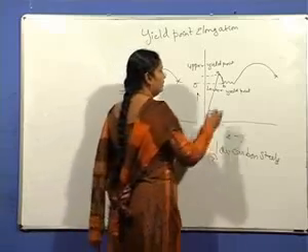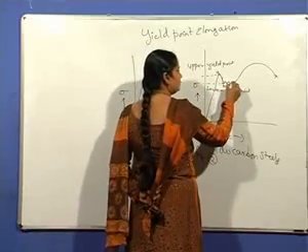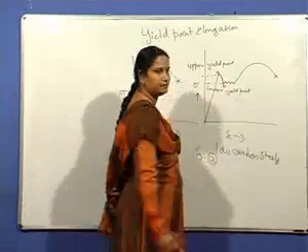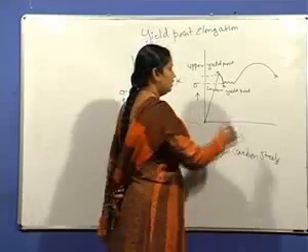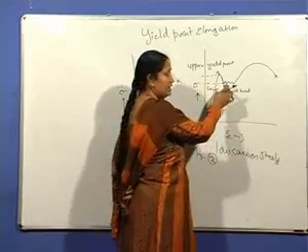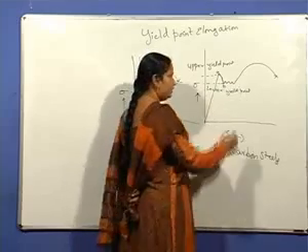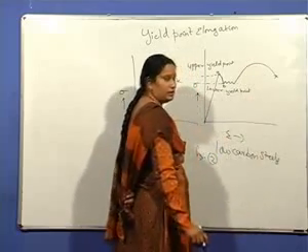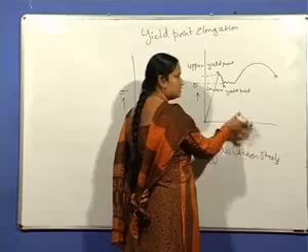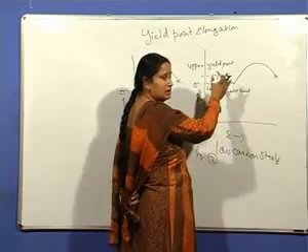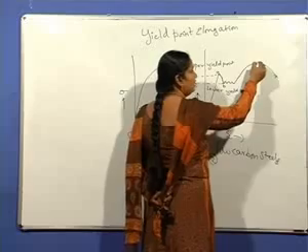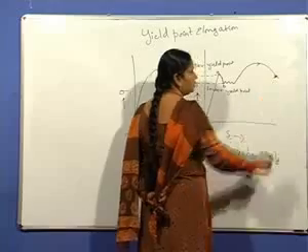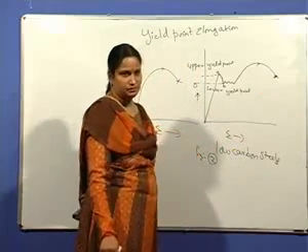At point B, the material undergoes yielding at constant stress. Under constant stress, the material undergoes elongation and then it continues to undergo strain hardening. That is, to cause further strain, you need to apply more stress, increase in stress to cause further strain, and again it reaches the ultimate tensile strength and the stress drops and it undergoes fracture.